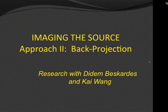So something much more interesting that we did, a more wave field approach to look at these earthquakes, was to use the methods of back projection. Probably most of you are familiar with Miyake Ishii and many others since, over the last decade or so, who have been using this back projection method with large regional arrays, such as the USArray or the Japanese Hi-net array, to image subduction zone earthquakes and to directly back project the observed wave fields to find out where and when the earthquake energy was coming from as a function of space and time. Now, I've been working with 2 of my students to do this with our recordings of the aftershocks of the Virginia earthquake. Next slide, please.